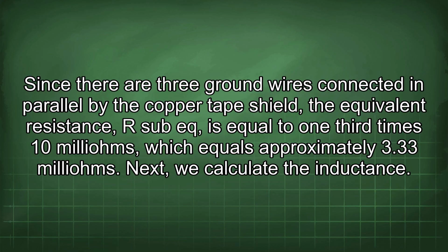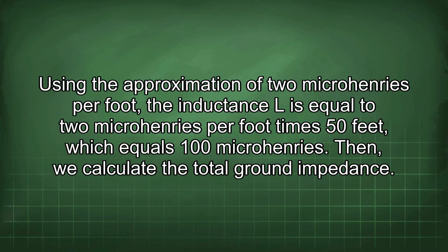Next, we calculate the inductance. Using the approximation of 2 microhenries per foot, the inductance L is equal to 2 microhenries per foot times 50 feet, which equals 100 microhenries.